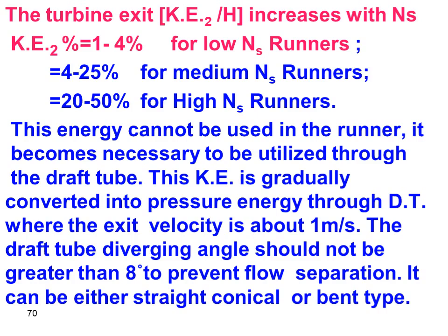The acceptable value of the velocity at exit can be 1 meter per second. If the exit velocity from the turbine at section 2 is, say, 5 meters per second, and you reduce it at the exit by using the draft tube to 1 meter per second, we have a drop in the kinetic energy, and at the same time a gain in the pressure head.